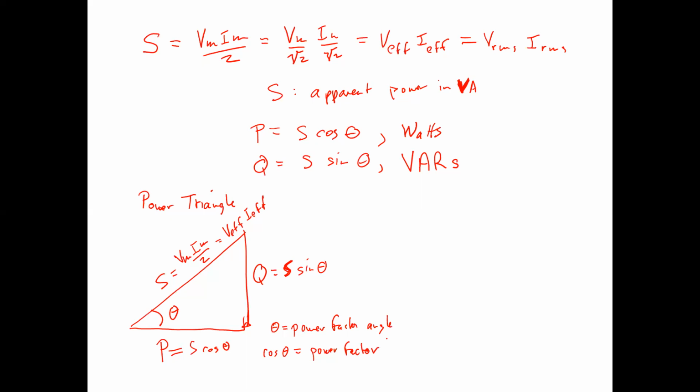That theta appears as the phase of the current, but that theta also happens to be the theta of Z equivalent, which you measured in the lab. Remember how you could convert that? That was the weird thing, right? When you measured the phase angle of the current relative to the voltage, it turned out to be the same as the angle of the impedance that you calculated, right? It was the same angle. And that's the connection between those two. So the impedance triangle has the same angle in it because that also relates the voltage and the current.